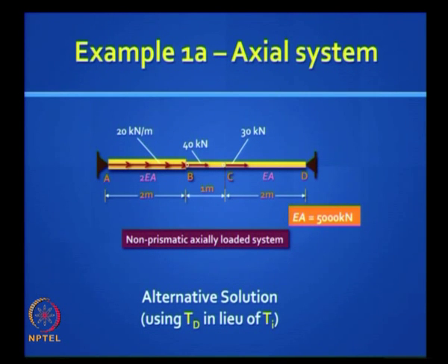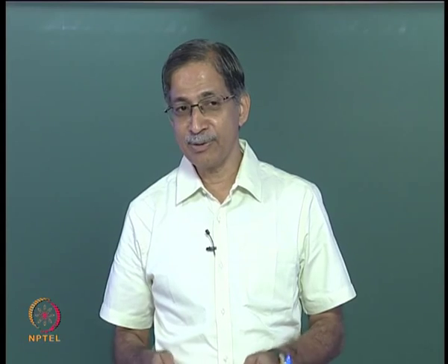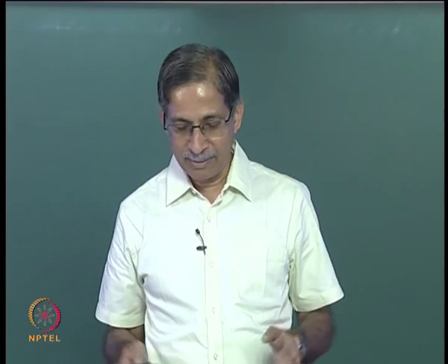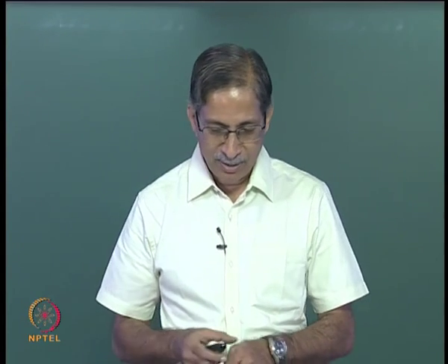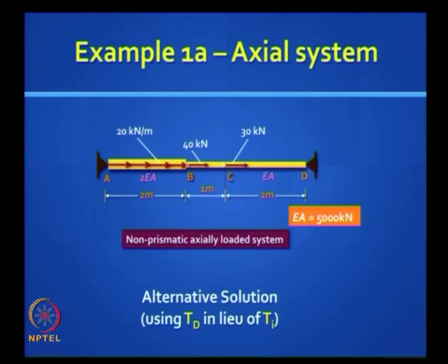This is actually easier to do by this method because you don't have to worry about the linking coordinates. But you are dealing with larger matrices. Of course, for this problem it's not very difficult because you have only two elements, but in real life problems, big trusses, it's a little unwieldy, but it's good for manual analysis.